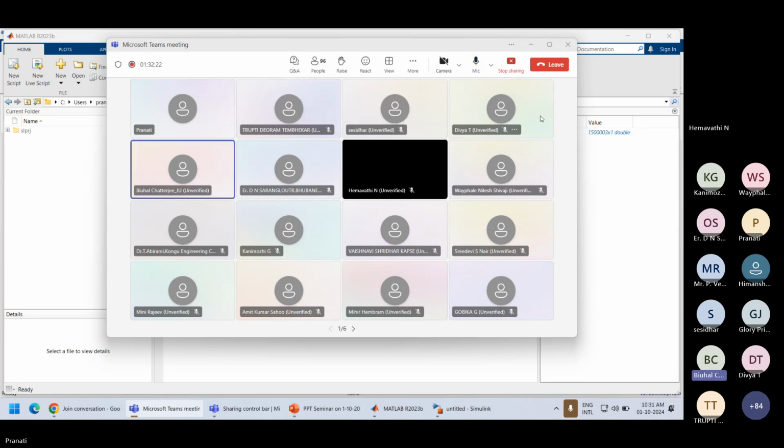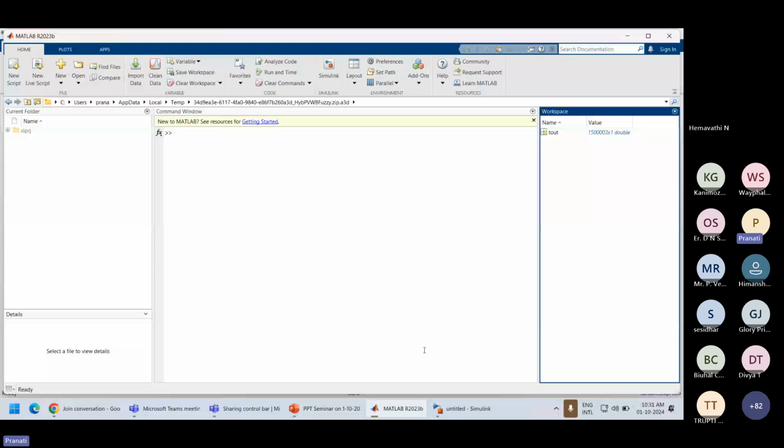In the fuzzy logic control you have shown the block diagram. There was a 1 by Z block, and after that there was an FLC, the fuzzy logic controller. If we want to implement that in Simulink, in which section do we do the logic part? And what does the 1 by Z block mean? 1 by Z represents the delay time only. It is a very simple delay time.